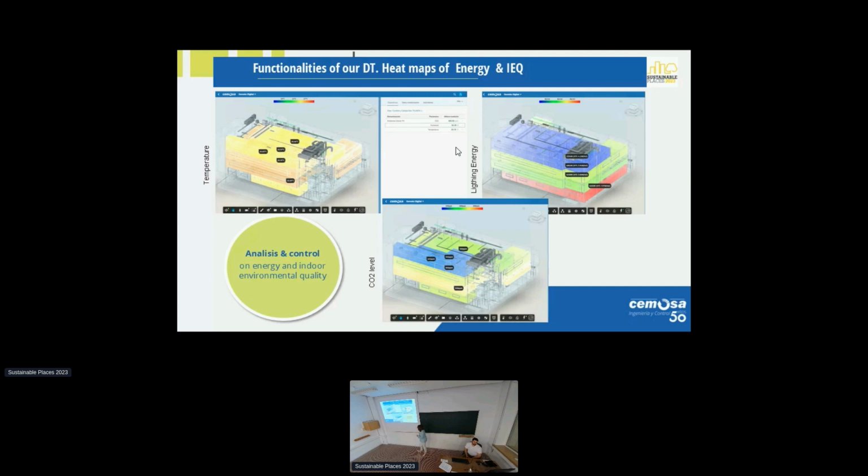And as you can see here, in the ground floor, the lighting behavior is not efficient. So people are consuming more than expected for the condition on this particular day, with the light coming from the windows and everything. And here you can see a heat map of the CO2 levels. Again, we have the boundaries. Again, if the CO2 level is too low, it doesn't matter. Maybe there is no one there, but we shouldn't reach over the red part.